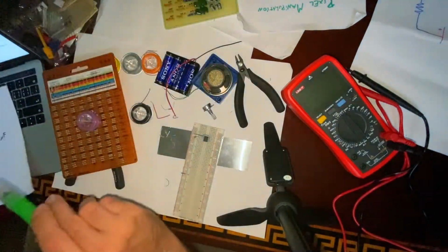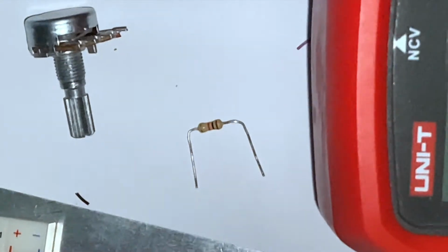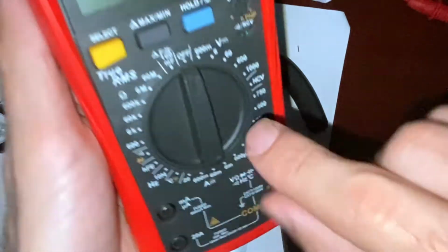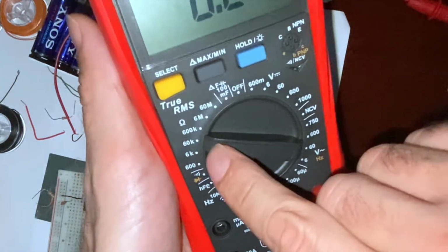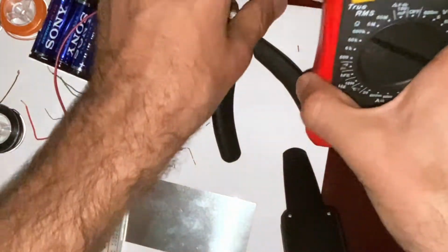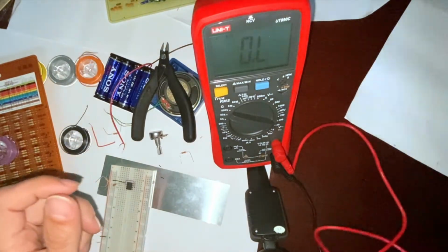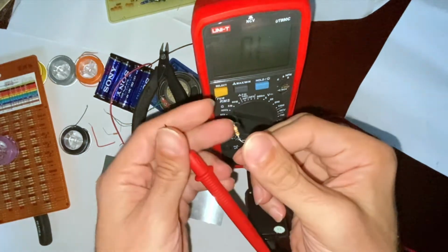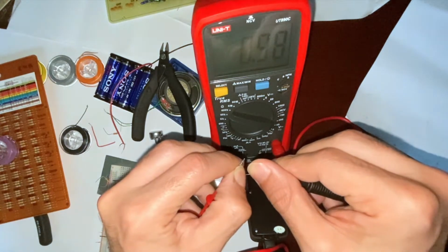And let's go on finding a 1 kilo ohm resistor. We already went over how to measure and how to read the color bands of resistors, but let's review. The test leads should be in common and ohm. Now we have this multimeter that is not auto scale, so we need to select something that is bigger than 1000. So you can start with the biggest, but I already know that eyeballing that resistor, it is not 1 mega ohm. So I'm going to use my fingers because the resistance value is not that big, and I will see that it says